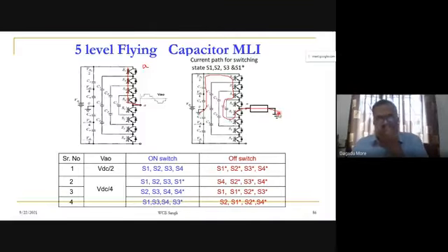So here, how many capacitors will come across the load? If you see, how many capacitors will come in series with the VAO point? Here we have seen these two capacitors and this. But this capacitor has the upper terminal positive and lower terminal negative, and this opposes this. So here two capacitors will provide a voltage equal to VDC by 4 plus VDC by 4.